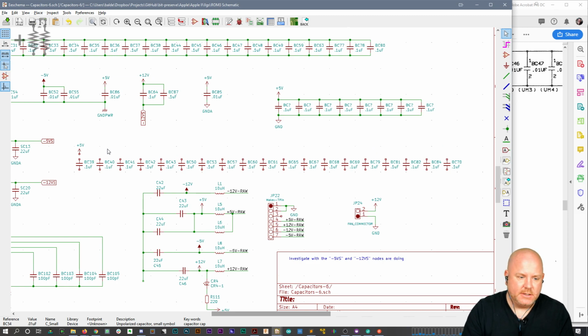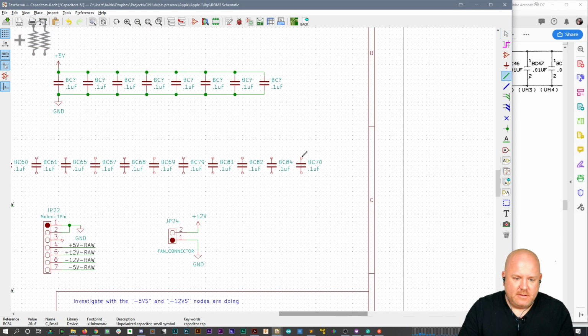No, they didn't, because they used DRAM on the C64 because the VIC-II chip, which does the video generation, has the DRAM controller built into it. And part of the reason that they were able to do that is because they took all the sound out of the original VIC. So VIC is Video Interface Controller. And because of that, they had enough room on the silicon for the DRAM controller. I think that's how it worked. Anyway.